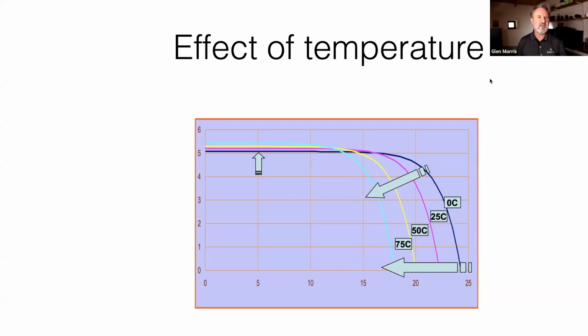So whenever you are writing on the compliance label for a solar PV system what the maximum open circuit voltage is, it's not just the nameplate rating on the back of the panels times the number of panels in series, which we'll get to in a second. It's actually the temperature compensated maximum voltage. So you need to consider how much rise you get due to the coldest operating temperature of the cells.